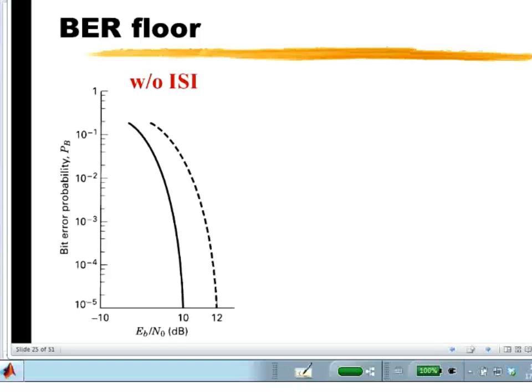And if I wanted to get back, well, this is not quite the right way of saying it, but if I had too much noise in my system, I could always raise the power of my signal to bring my signal-to-noise ratio back in line to achieve whatever bit error rate I wanted to, so that you can overcome noise problems with signal power.